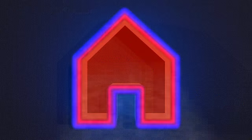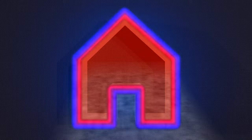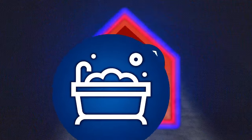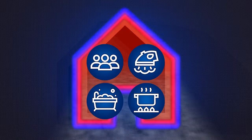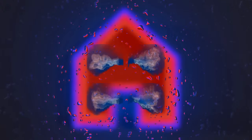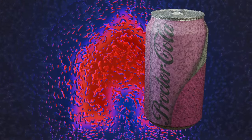The inside of the building also contains a certain amount of moisture. This comes from virtually any activity the occupants engage in. Cooking, baths, showers, even simply breathing all elevate the moisture level internally, raising the humidity. The warmer air is, the more moisture vapour it can hold, and as it cools, it loses this ability, leading to condensation forming on colder surfaces, like on a cold drink can or a car window.